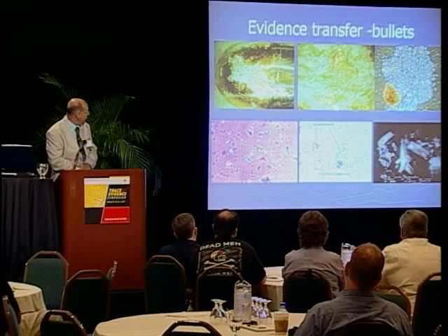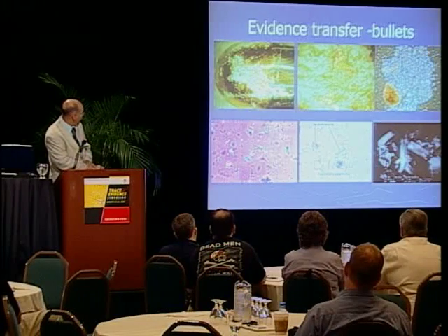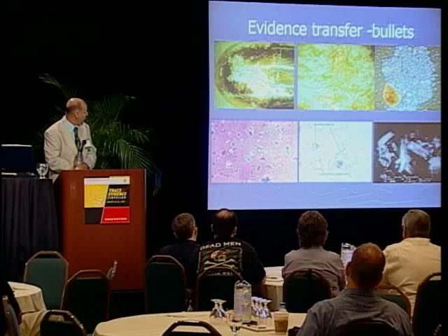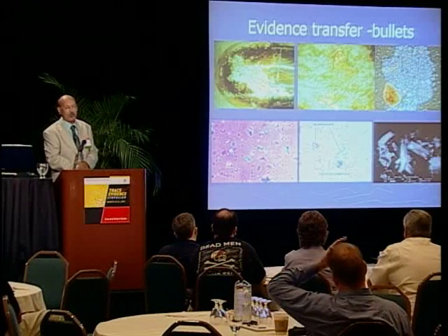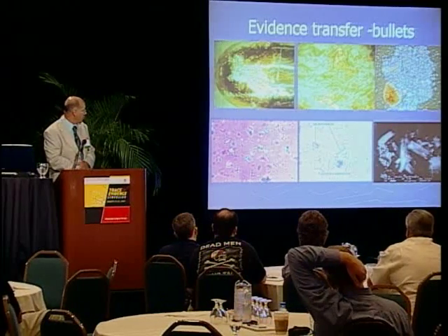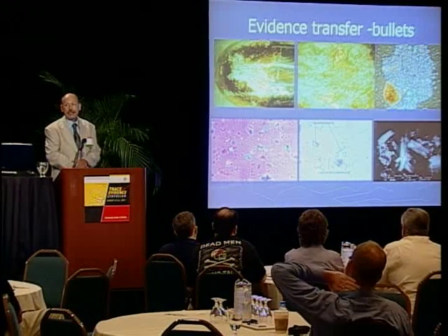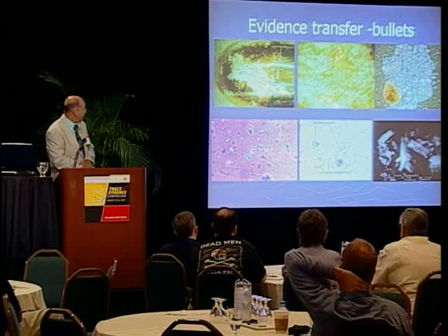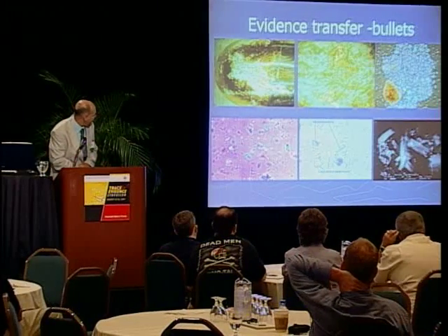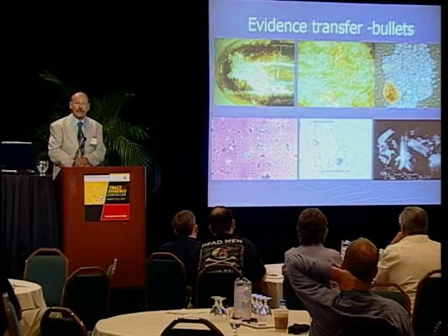But at higher magnification, using 100x oil immersion, you can start to actually see some of the individual particles of gypsum, which is a major component in sheetrock and wallboard. But there are some trace components too, which can occasionally be found, some other hydration states of gypsum, such as hemihydrate and, I don't have anhydrite in there, and also little pieces of calcium carbonate. And then again, if you want to carry it another level, you could do electron microscopy and look at the structures of the gypsum and elementally analyze it, containing calcium and sulfur, of course.